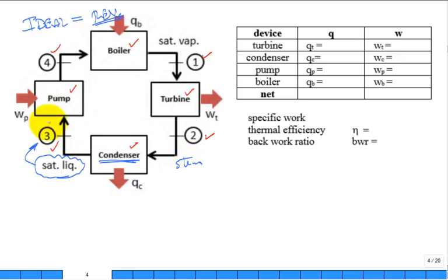Remember, we analyzed the difference between a compressor and a pump, and you really like to feed liquids into pumps. Kind of the high end of a liquid is not a subcooled liquid, but a saturated liquid. Now, what can come out of a boiler? Well, superheated steam. But the lowest quality the superheated steam could have would be saturated vapor. It would be on that cusp.